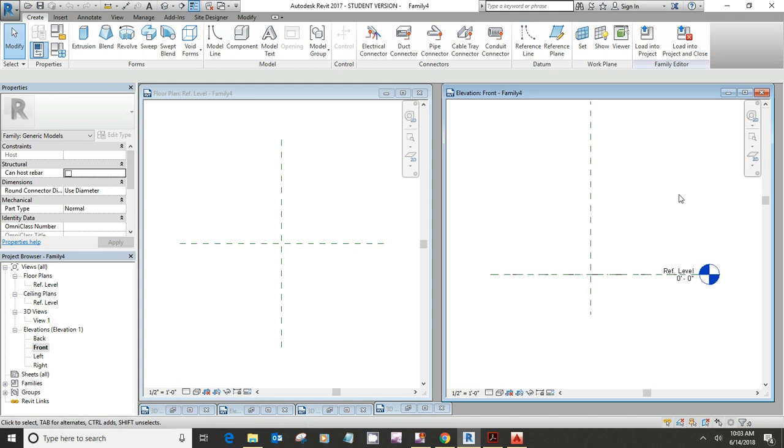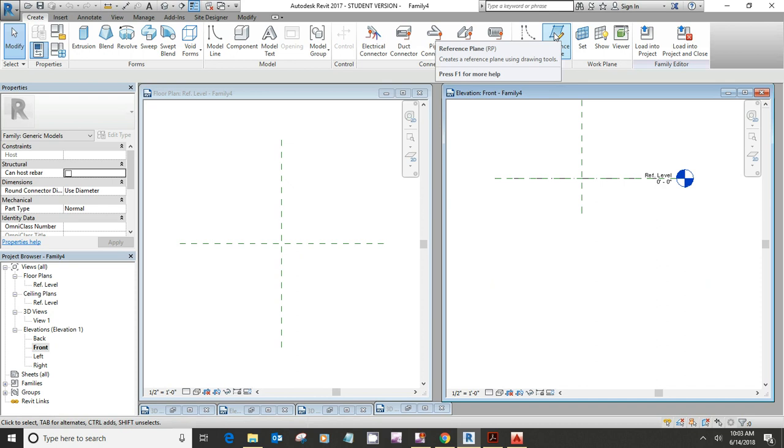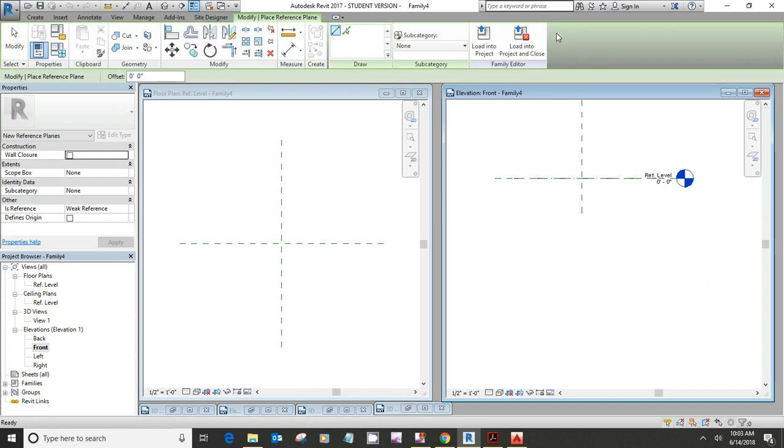All right, we want the center of the hole for our pipe to be right here at reference level 0 and centered left to right. So I want the hole to be centered there, which means I need a work plane down here below, or a reference plane, to draw my wall and my footing on. So I want to create a reference plane, and let's see, I'm looking at that chart, the PDF. Dimension E for a 24 inch was 42 inches down.